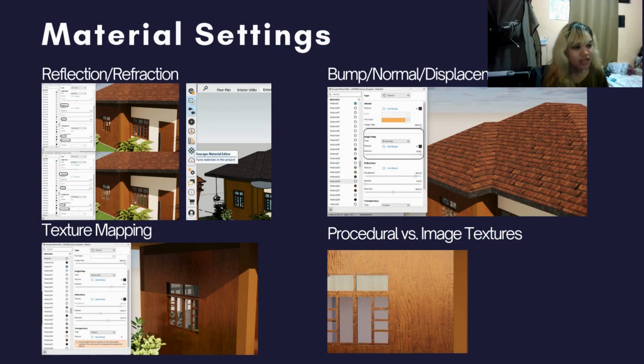This is your material setting. You can find Enscape Material Editor back in your SketchUp from your Enscape plugins. Here you will be able to enhance how your material will appear on your render. You will first select your material by clicking Use Albedo. You will now use the material picker to choose which material you'll edit.